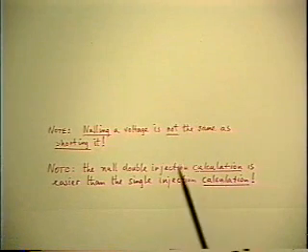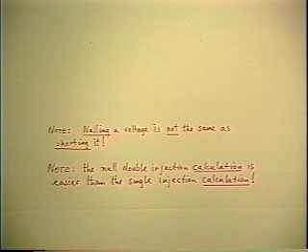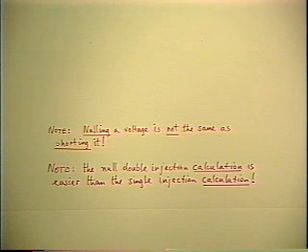There's a few things along the way that it's worth pointing out. Nulling a voltage is not the same as shorting it. If you short it, then for sure you've nulled it. It's going to be zero. But it's not zero because you cancelled out two opposing currents. Notice that after you've nulled it, then you can short it. But you don't achieve the null by shorting it.